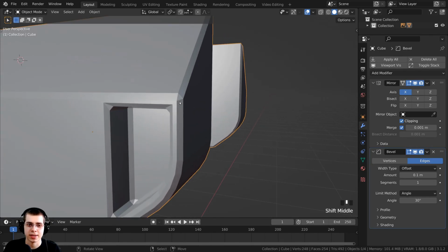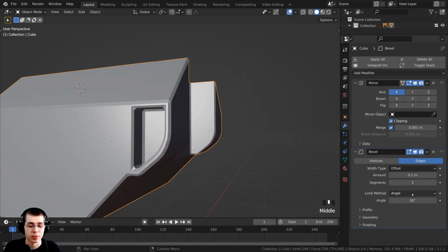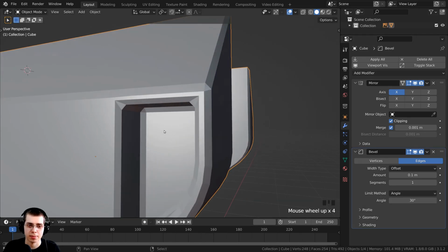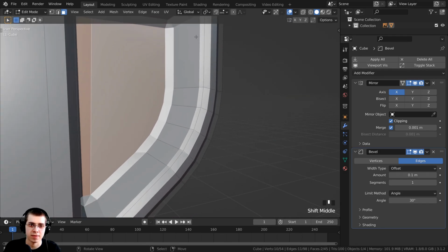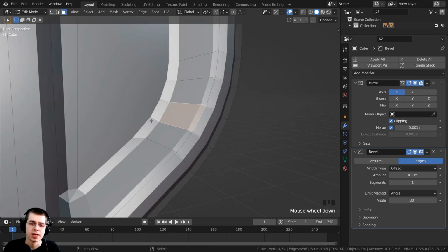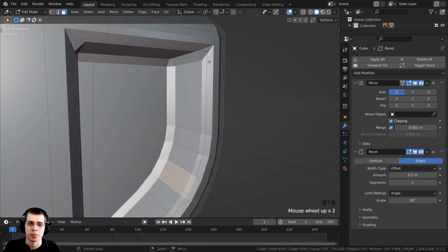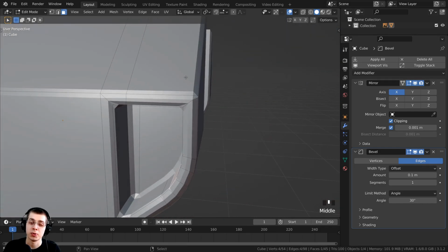So now if you look around here, you can see it's adding that sharp bevel to all of the edges. Now there also is this angle limit right here, and so what this is going to do is it's not going to add bevels if the angle is very small. So if I look right here, you can see it's adding bevels there. It's also adding bevels here, like this face going down to this face, that's like a 90-degree turn. But then if you look right here, you can see that this is a very subtle turn and it's a very subtle curve. And so because we have the angle limit on, which is on by default, it's not going to add a bevel right here on these vertices, and that is what I want because I wouldn't want that to look very sharp. But then right here where it's very sharp, where the mesh is kind of turning like right here and all the other areas, I do want that to have a bevel.